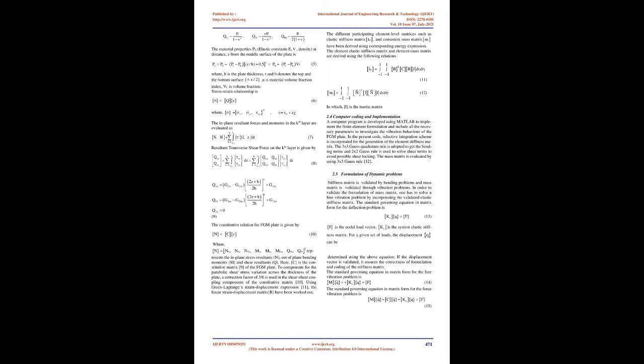The plate was considered as homogeneous and material composition was varied along the thickness. The Young's modulus was assumed to vary as per rule of the mixture in terms of the volume fractions of the material constituents. Hughes and Cohen developed the heterosis element and elemental equation.